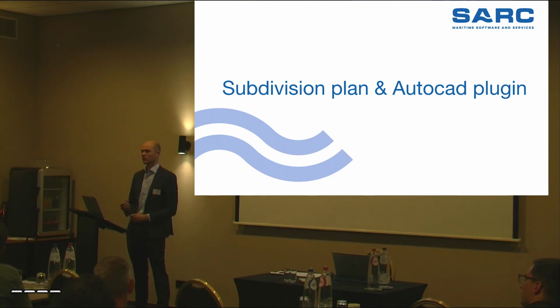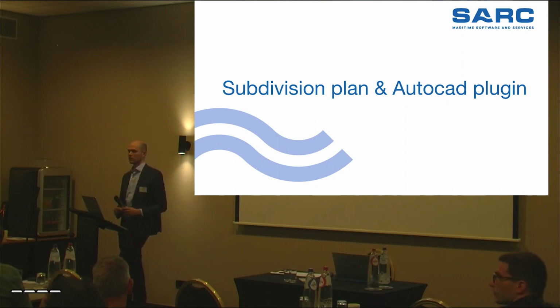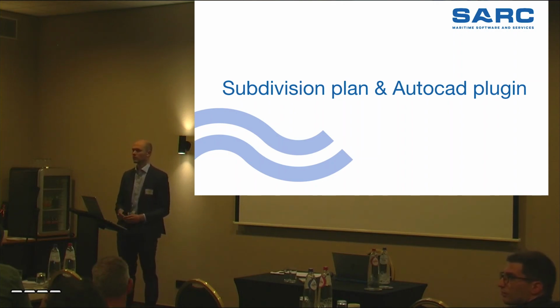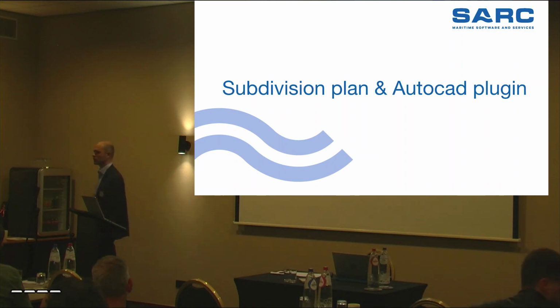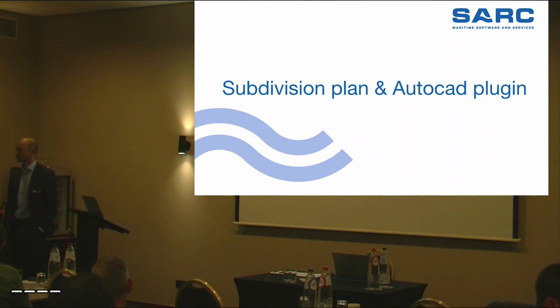You can copy the weight and the center of gravity for the weight item into the light ship, because if it's a tank, you could empty it and load it, which is not allowed for the light ship weight because I changed that. So the tank can be changed and the light ship weight cannot. These two cannot mix, but you can copy the weight inside that thing into your light ship.